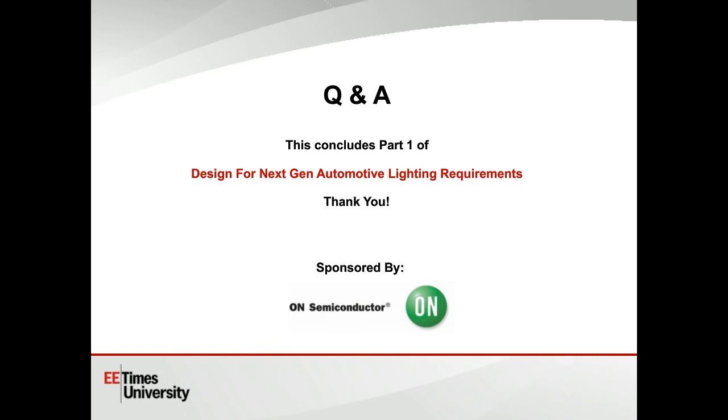What are some of the ways in which functional safety can be addressed with LED lighting? Redundancy is kind of difficult to do because of space. So is it guaranteeing a certain level of lighting? Yeah. If we look at a modern state-of-the-art automotive headlight, you will find that there are multiple different LEDs for different functions, and that provides built-in redundancy. So, for example, if your high beam headlight LEDs fail, you can automatically switch to a low beam LED headlight while alerting the driver.